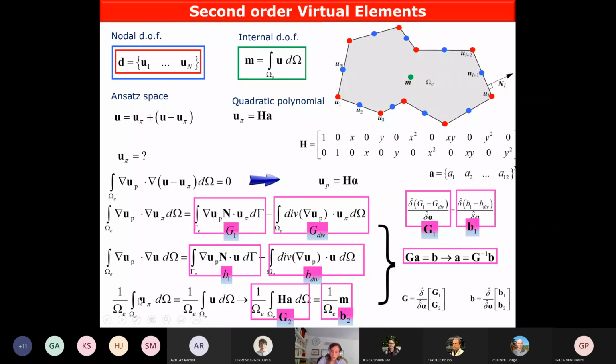The extra requirements are that over each element, the mean value of the projected displacement is equal to the mean value of the discrete approximation solution in terms of displacement. By combining the set of 10 equations and the set of 2 equations, it is possible to obtain a final system of 12 equations in 12 unknowns, and to obtain the coefficients A.